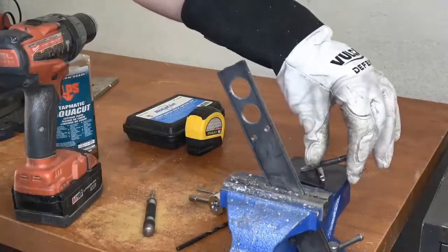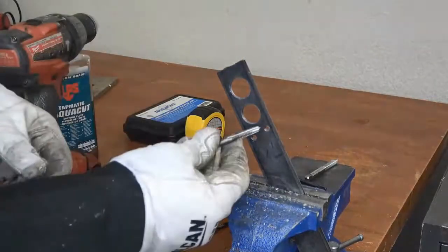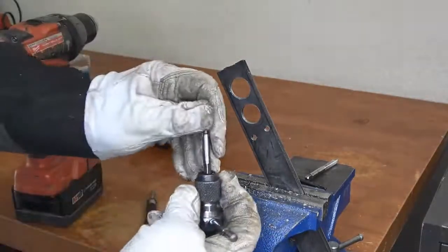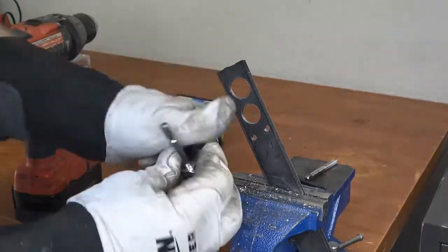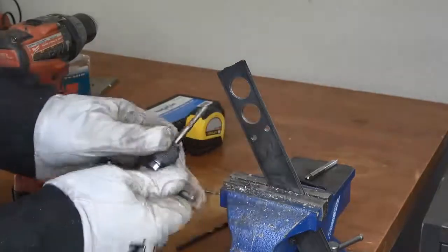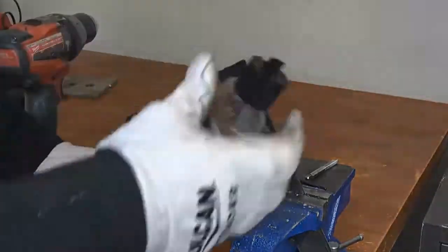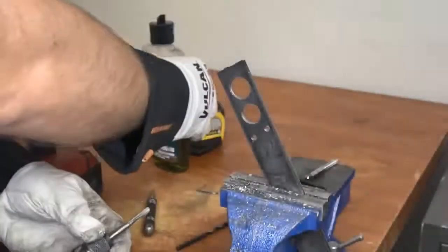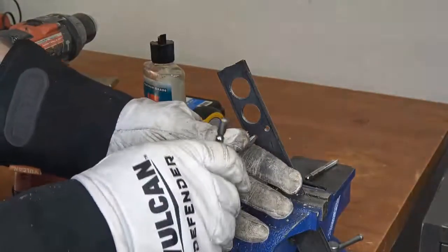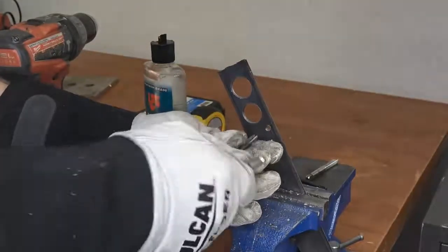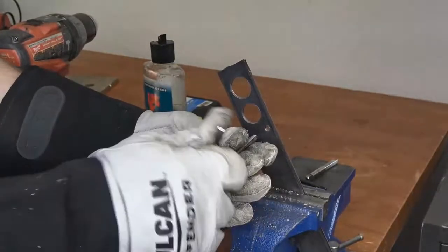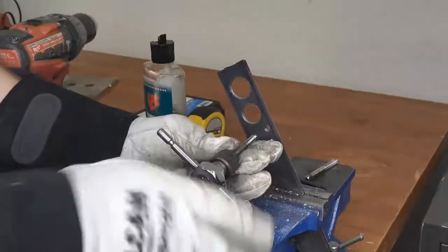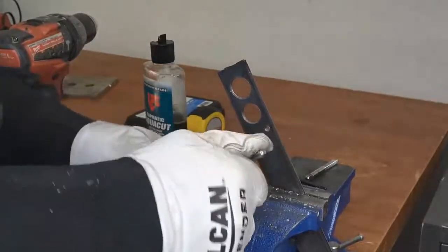So here is kind of a compare and contrast. We're going to use the taper tap with a tap wrench. Some cutting fluid. And you get to a point where it loads and it binds and you can't go any further, and you have to back it up to break the chip off.